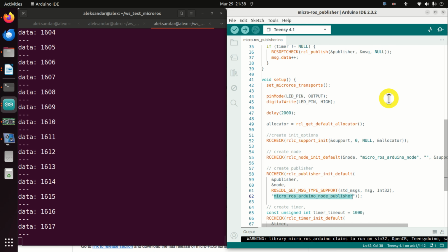The complete idea of this video is to teach you how to run a publisher node in Arduino and how to use micro-ROS2 agent and ROS2 Humble to receive the messages from the Arduino node and to display them on the computer screen. This can be seen as a Hello World program of computer Arduino interface.